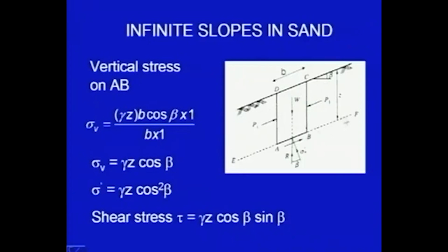And here I have taken a plane of rupture. You can have it, in fact, in case of the hills etc., there is a hard stratum available at a certain depth. So, we can use that stratum also. So, this is the surface at which we are considering the stability.